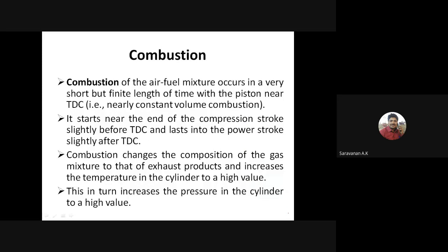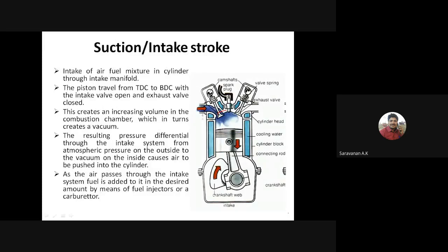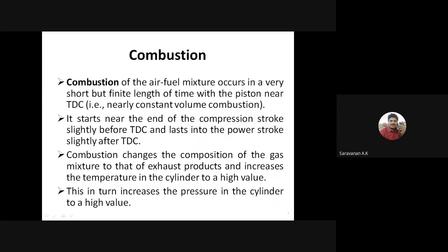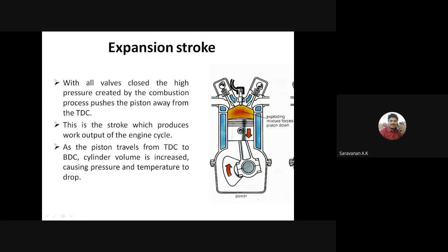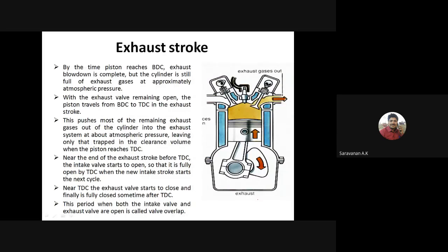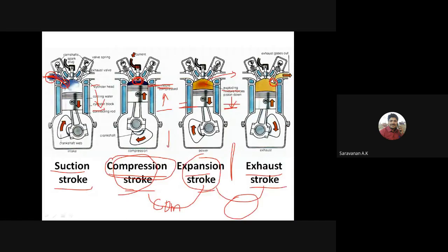So these are the four strokes, right? The suction stroke, then the compression stroke. In the compression stroke, what will happen? The piston pushes the air-fuel mixture, so the temperature as well as the pressure will increase, right? After that, the combustion process, then the expansion stroke, then the exhaust blowdown process as well as the exhaust stroke. So all the strokes are here, right? Is it clear?